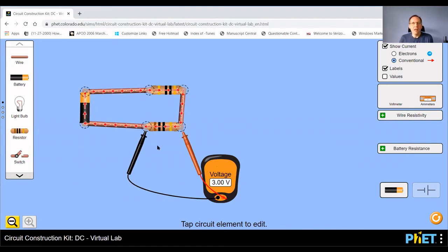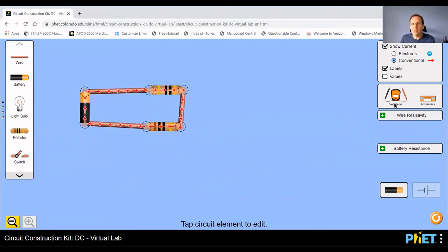And then to measure the currents, remember, you want to measure the current here at this location, at this location, and this location. So you have to separate this, cut it, maybe shrink this a little bit, and then grab your ammeter, stick it in the circuit, and then that would be I1. That would be at that first location, I1. Then you do the same thing here, I2, and then I3. Okay, so that'll give you all of the values that you need.